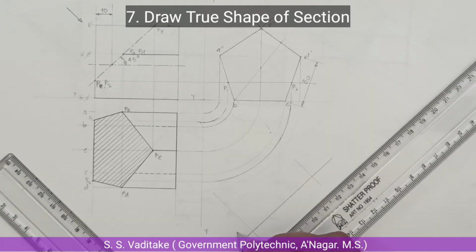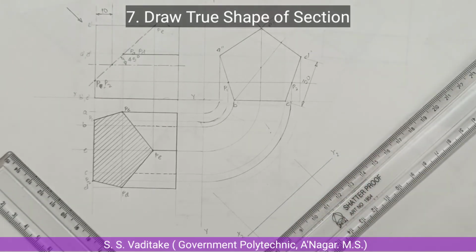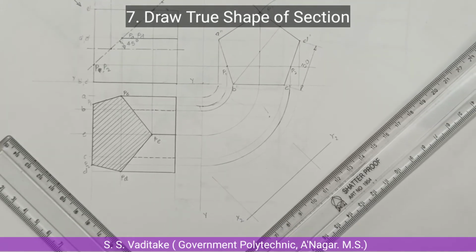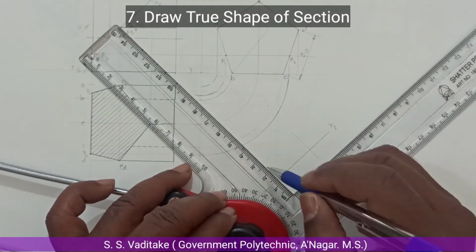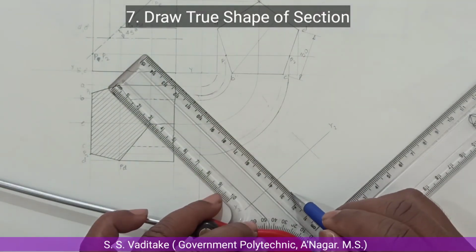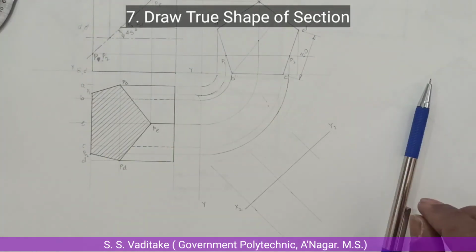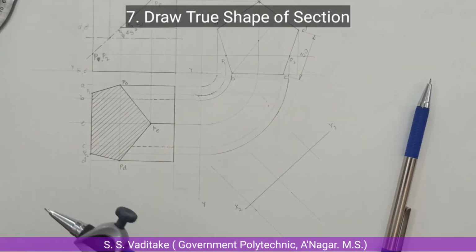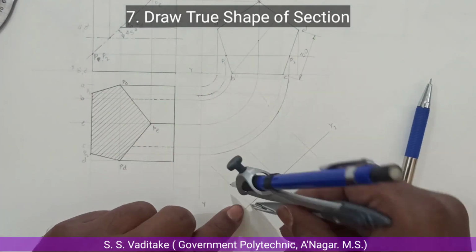Now draw x1, y1 as a new reference axis. With the help of this, we have to draw the true shape of the section. These three projection lines at a right angle to x1, y1 are drawn, which pass through the cutting points.